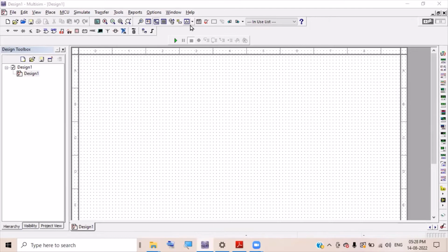Good morning, everybody. Today we will see how we can complete 6 electronic circuit analysis experiments using NI Multisim. So first, let us start with the common emitter amplifier. Usually in the common emitter amplifier circuit, we make use of voltage divider bias. So let us start constructing the transistor in voltage divider bias.